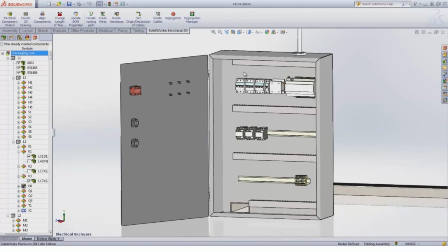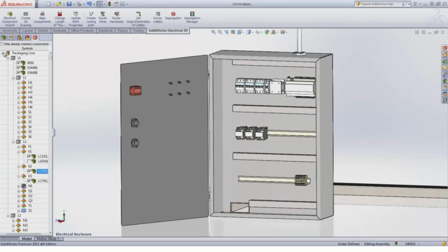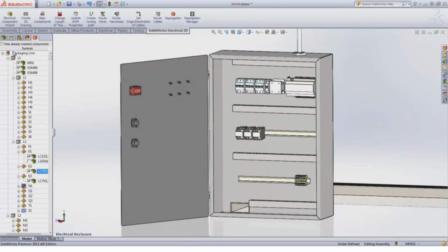The remaining electrical components can be positioned very quickly using smart mates, or can simply be selected if they were previously placed. In fact, creating the electrical panel with ducts and rails, or wiring all the components, can be done very quickly with the numerous intuitive tools that are included. The align command, for example, lets you space these connectors precisely along the DIN rail mounting.